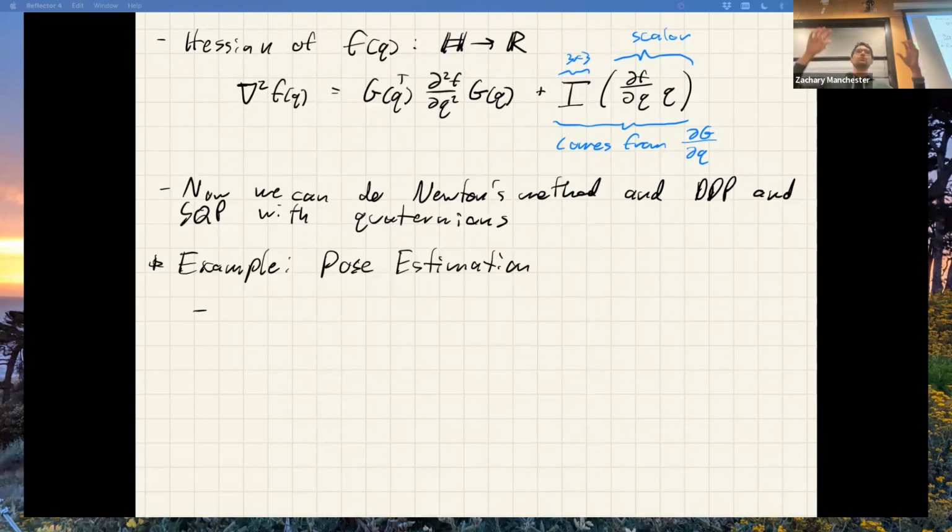So I have those vectors, unit vectors. I know what they are in the world frame for my map. I know what they are in the body frame for my camera observations. So I have a collection of vectors where I have them both in the world frame and in the body frame. And the problem is, okay, given all those vectors, I want to figure out what my attitude is from the vectors. So we're going to write that down as a least squares problem over a quaternion.